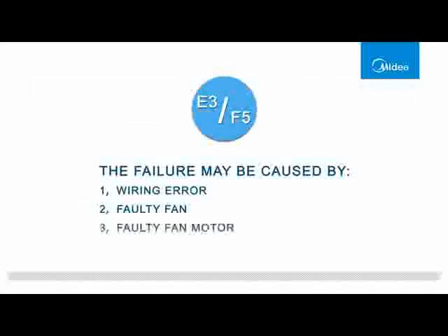The failure may be caused by: 1. Wiring error, 2. Faulty fan, 3. Faulty fan motor, 4. Faulty main PCB board.